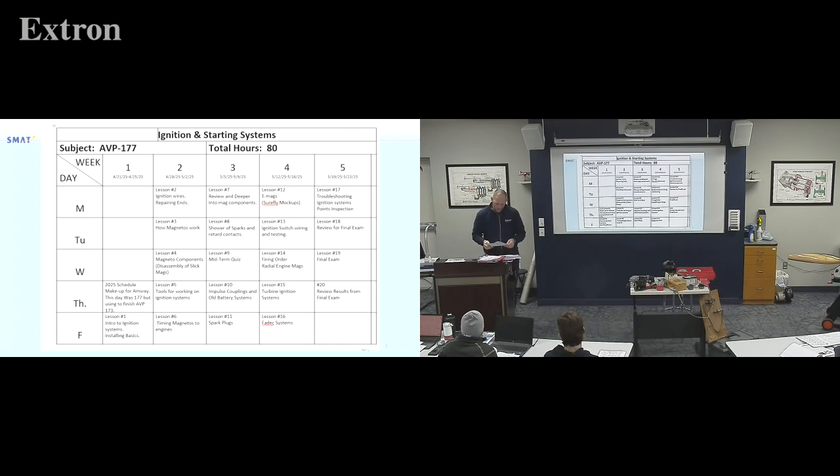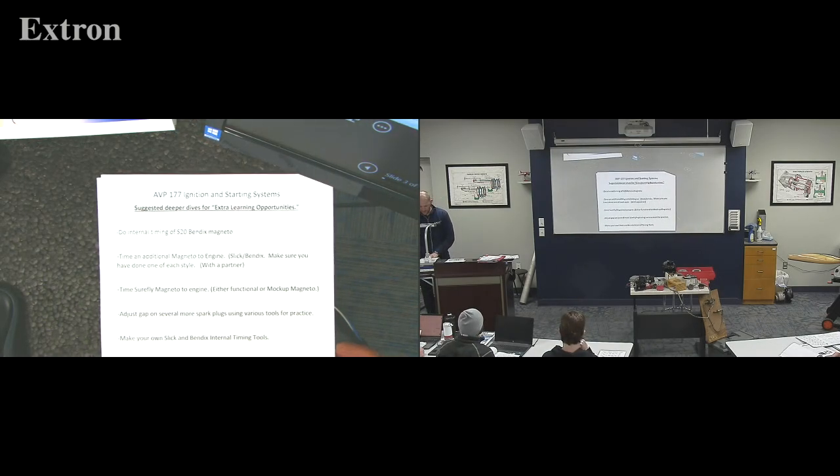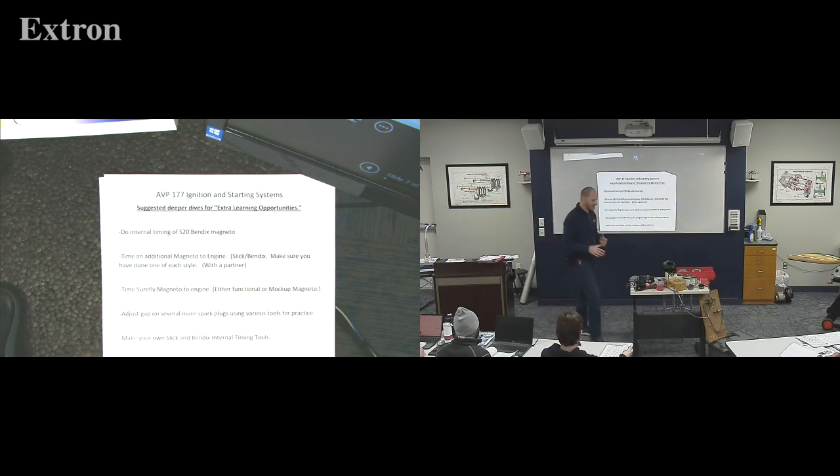So, with that, and we're gonna go over what they all are in a minute, you've got your extra learning opportunities sheet here. I wanna go over your extra learning opportunities sheet, kinda make sure you know what's going on with each one, so that you can do it. Internal timing, we'll talk about later. When we say internal timing, basically we're saying you're adjusting the points on the magneto to time the points when they open in relation to this thing going around.